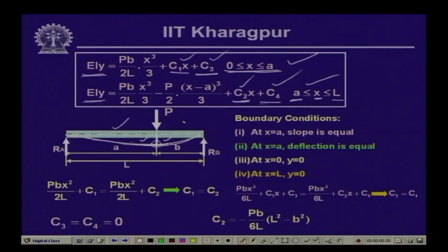It is not discontinuous, though we are using two different functions for evaluating moment and correspondingly the deflection curve, physically the beam segment is not a discontinuous one. So, when it deflects, the deflection curve has a continuity at that particular point, or the boundary point between the two expressions which we are using.